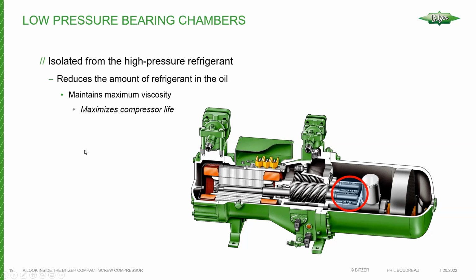That'll indicate the compressor turning in the right direction. If it starts to increase, or more commonly, you don't see it do anything, maybe it just flutters a little bit, that's an indication that two of the wires need to be reversed so that you can reverse the rotation of the compressor. But then repeat the test again, definitely, just to be sure.